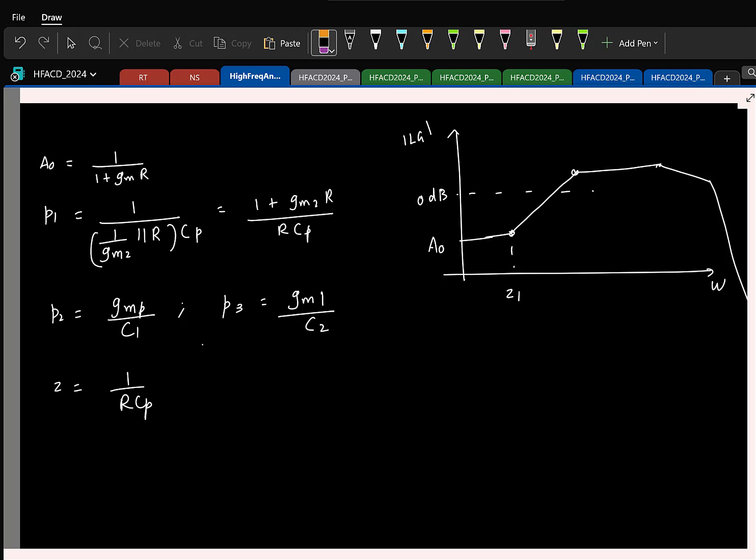So the magnitude of the loop gain at some frequency can easily become greater than 1 and things will become unstable. Let's say you are not putting an extra capacitor in CP; CP is an existing parasitic capacitor and you see that this is happening. What is the fix?